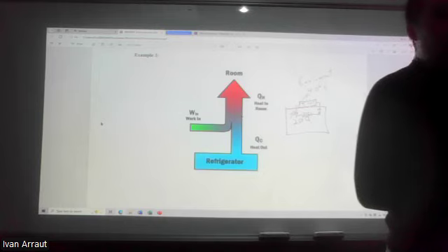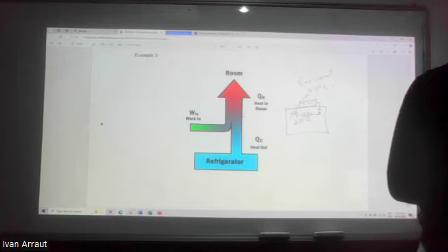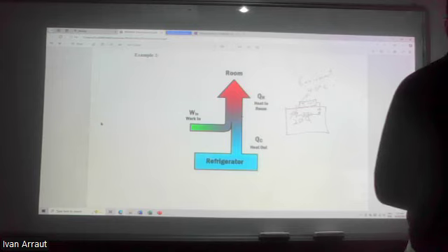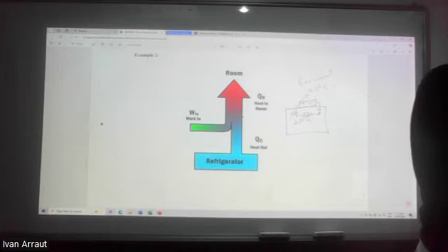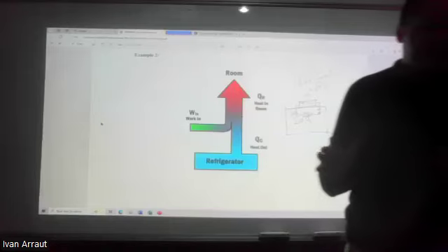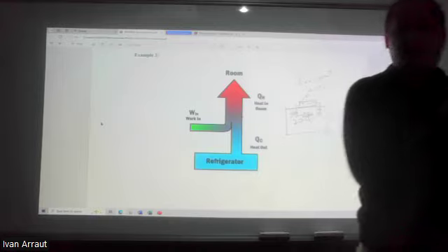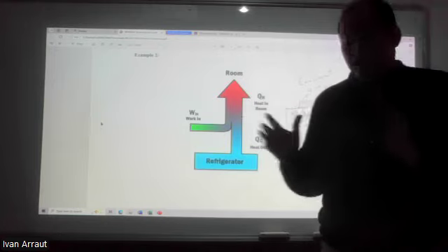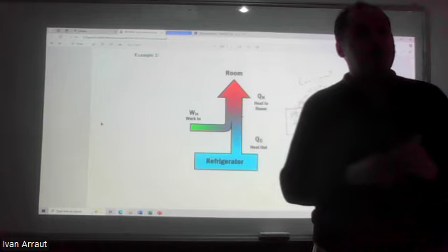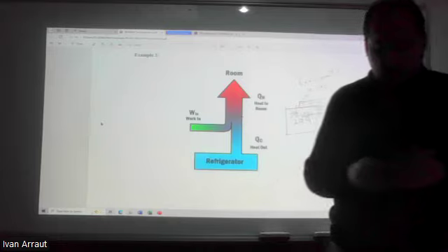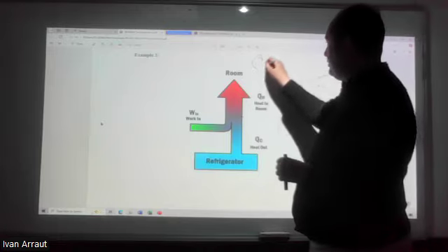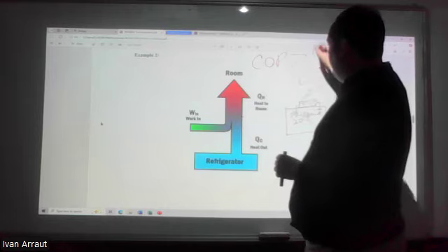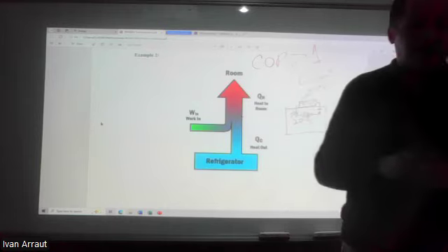In the case of air conditioners, we don't use efficiency for evaluating how well the air conditioner operates. Efficiency is for the engines, motors. And we compare the efficiency of the motor not with 100%, but with the ideal Carnot cycle, which I will probably explain in the next session. In the case of refrigerators, we use something called coefficient of performance, COP, which should be larger than 1 if you design the air conditioner well.